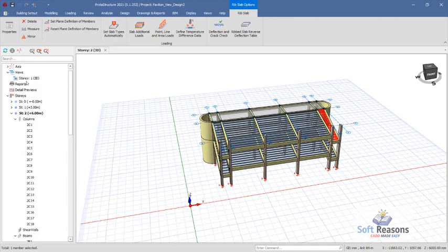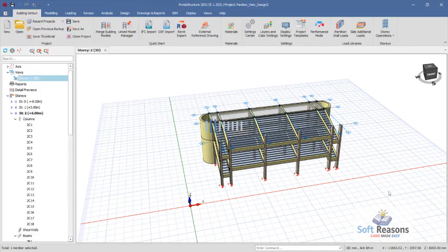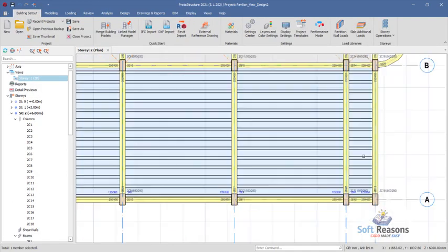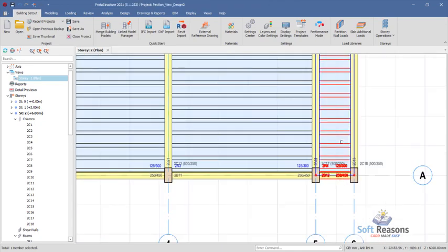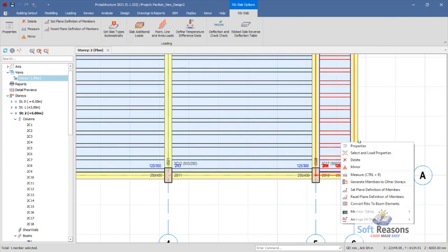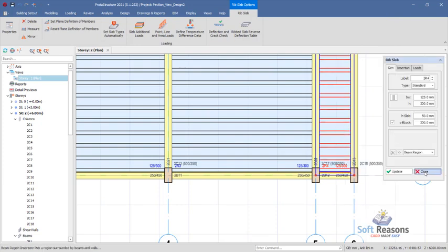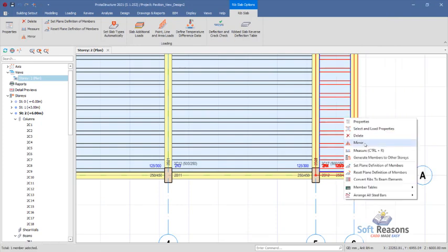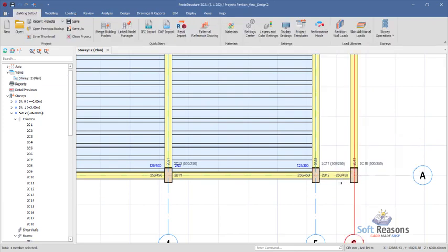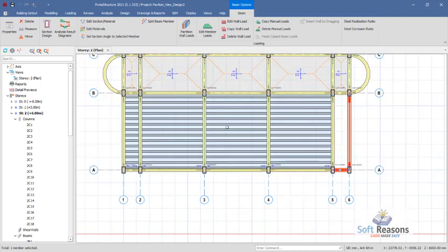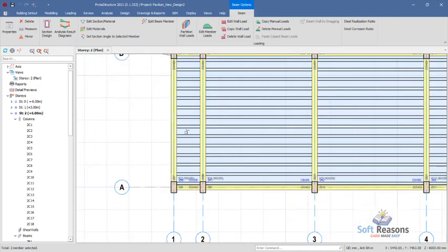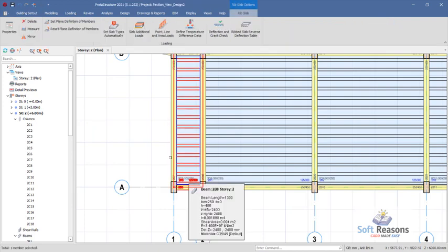At the plan view, before we can do that effectively, we need to get rid of these beams, because this plane is not actually showing us. There is no way you can get the plane, so you have to delete the slab at first. You get the slab deleted just like this, and then you also have to delete the beams first, and after deleting it, we will reinsert all of that successfully.